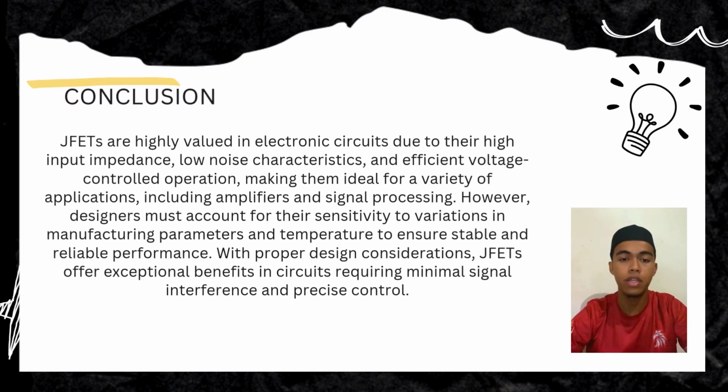JFETs are highly valued in electronic circuits due to their high input impedance, low noise characteristics, and efficient voltage control operation, making them ideal for a variety of applications, including amplifiers and signal processing. However, designers must account for their sensitivity to variations in manufacturing parameters and temperature to ensure stable and reliable performance. With proper design considerations, JFETs offer exceptional benefits in circuits requiring minimal signal interference and precise control.